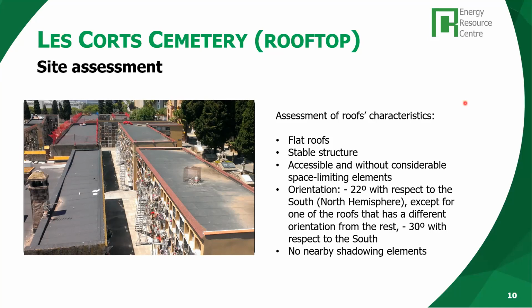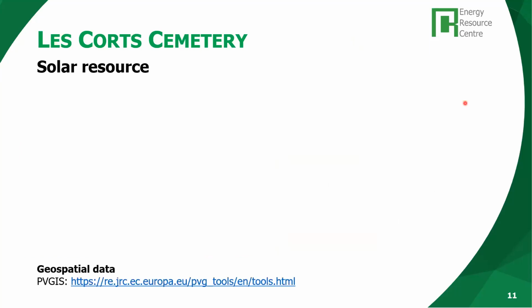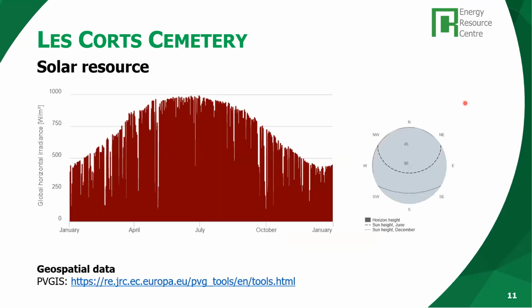Remember that all the modules connected to the same MPPT tracker have to be at the same orientation and inclination. This is what you were talking about, the orientation and the inclination, and we have to be very careful with this. Exactly. Okay, then of course the solar radiation in Barcelona was checked.